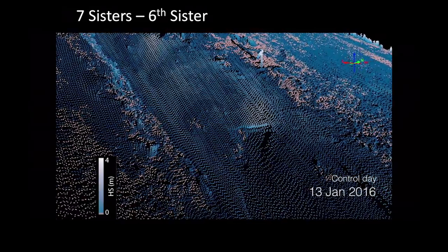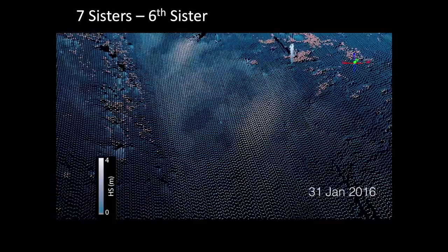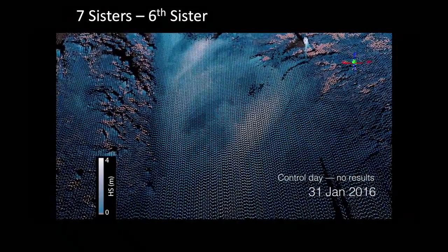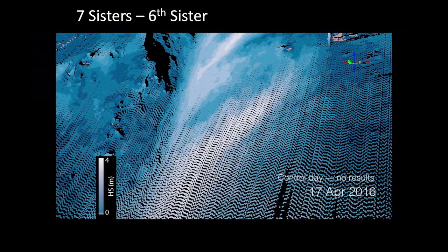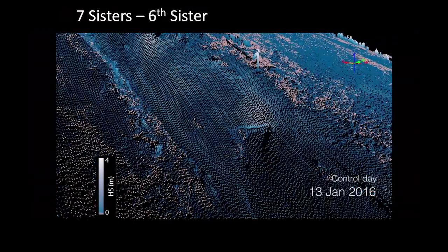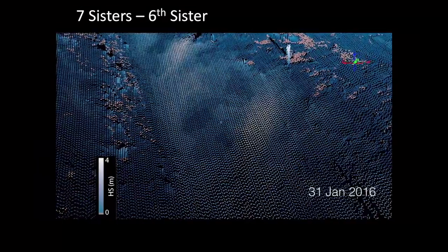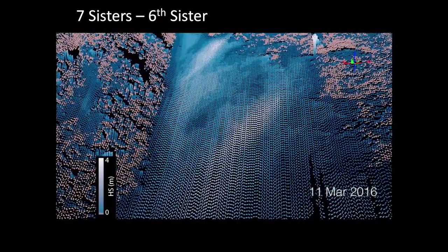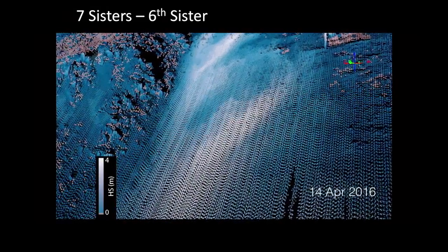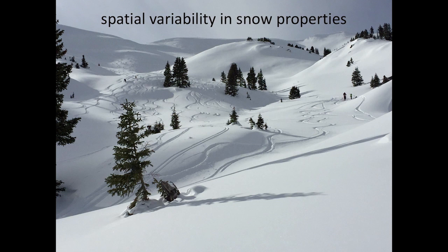So one of the potential operational concerns with a GASX system is if you fire it too frequently, it actually just serves to work harden and pack down the snow that's directly under the exploder, and therefore renders it less effective at communicating that shock wave to the rest of the snowpack around it. I won't say that this is a conclusive result that that's happening here, but there is some pretty good circumstantial evidence given the location of this drift, literally directly below the exploder. So that's another thing that we're going to monitor in the coming years as well.